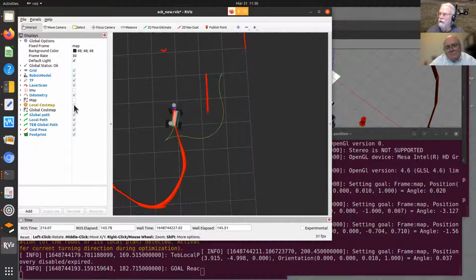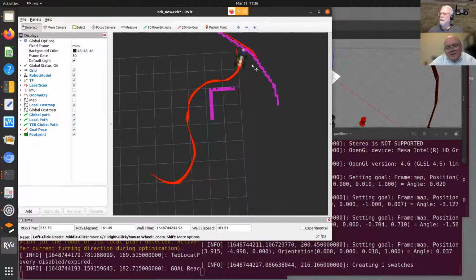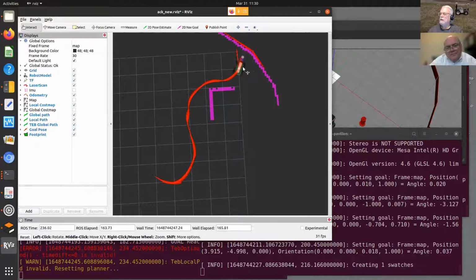And there's my local cost map turned on. So the laser scanner is running, and see it's driving around. I might clip the edge of it there, we'll see, because again, that green box is telling me that's where it thinks the outline of the robot is, and it's not actually there. That was fantastic. So I was surprised that works.